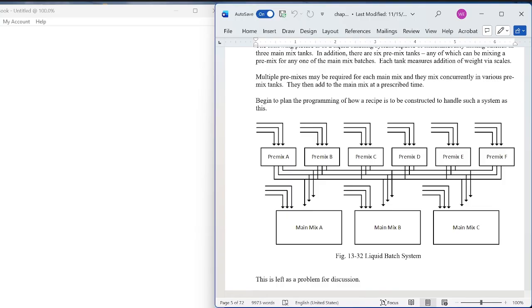What is this stuff doing, Ben? What is this going to? These are the liquid binder systems that go out to the various lines where they're making fiber for fiberglass. And they coat with this material, and it's kind of like snot. It's a sticky material, but it coats the fibers so that fibers, if they're not coated with binder, will break. But if they're coated, they will rub against each other and never break. And that gives fiberglass its strength.